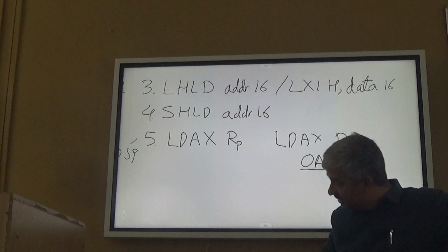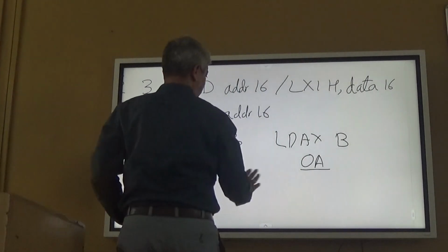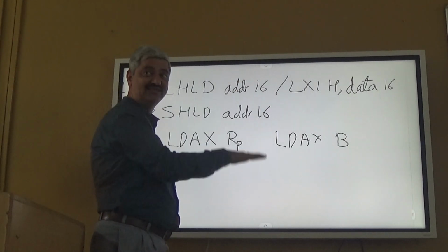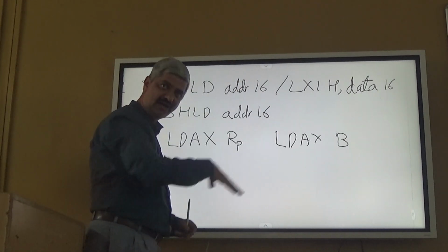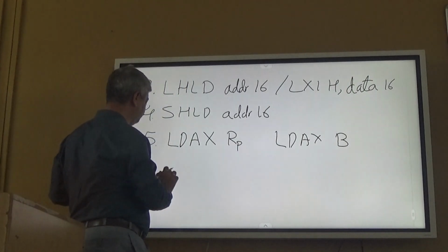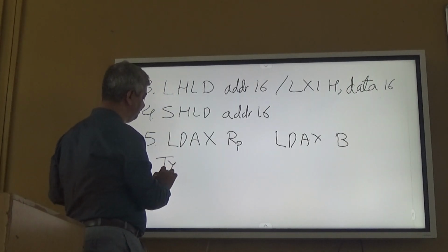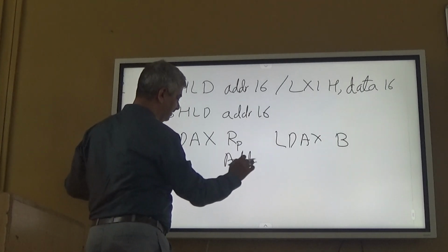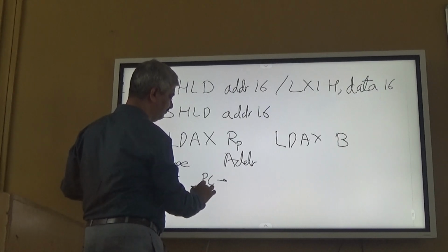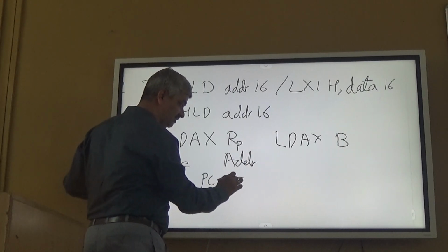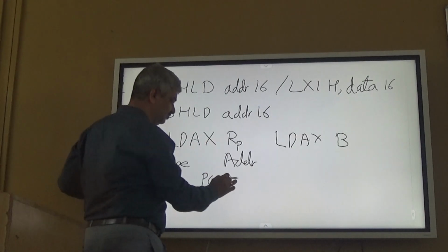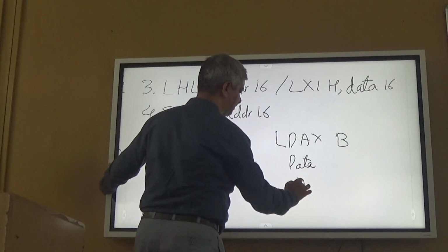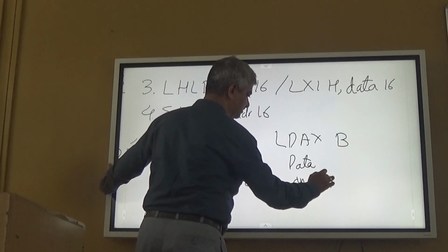So this is very important. I take a break in the sense, not for the lecture, a break to explain the instructions, and we deal with this instruction right now. Type is obviously opcode fetch. Address is obviously program continuity, let it be anything. So let it be 1000. Data is 0A. That goes to the instruction register.